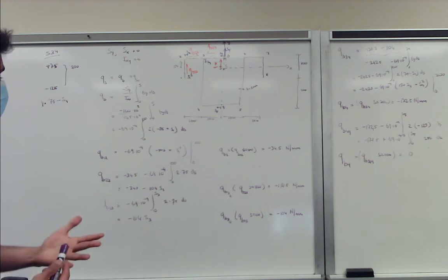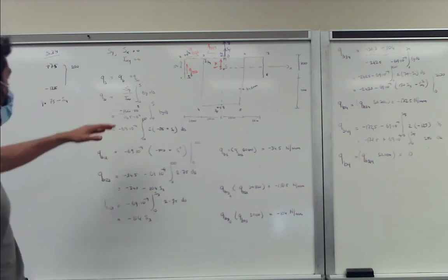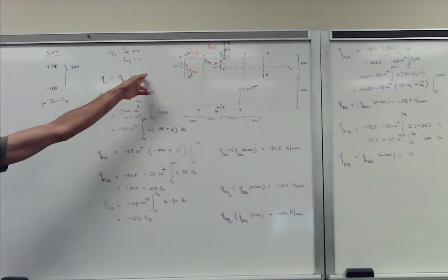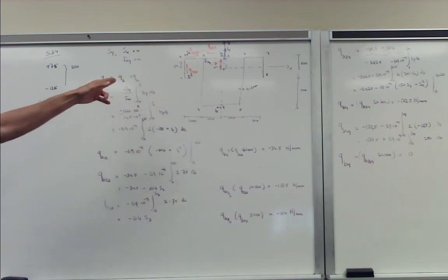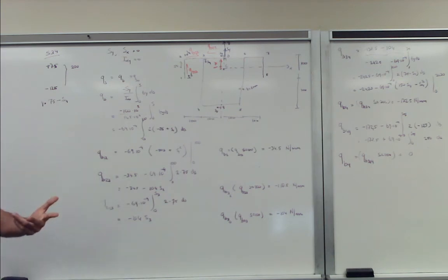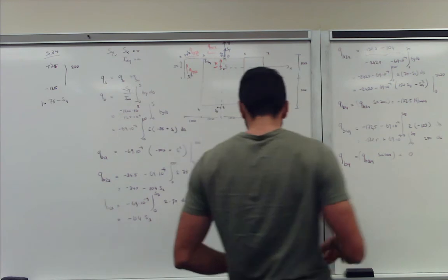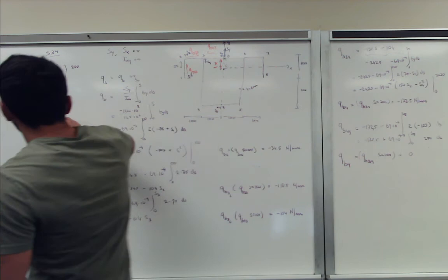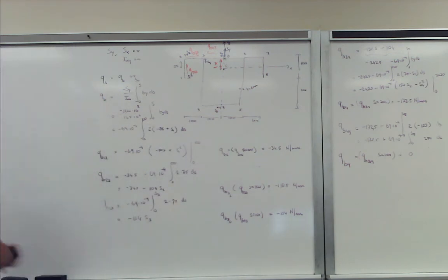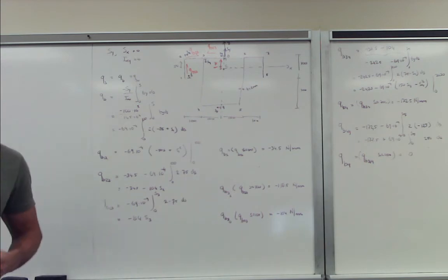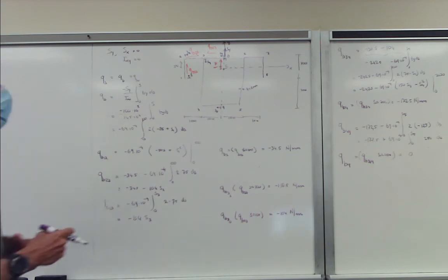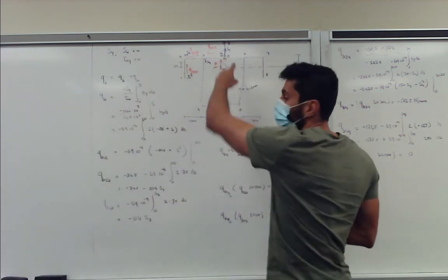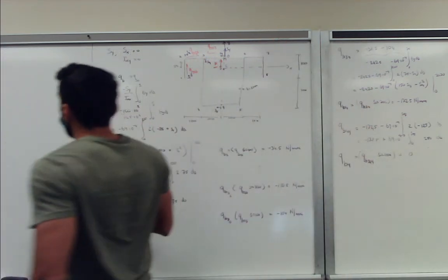So then the question is, well, we made a cut, so we have to calculate the correction shear flow, right? So in this case, we have a special case. We can do the calculations, and if we actually do the calculations, let's see. Let's do it on this side. I want to keep this available. Okay. So let's pick a location when we take the moments around. Okay. Let's pick point 0 because we have the shear force going through that location.